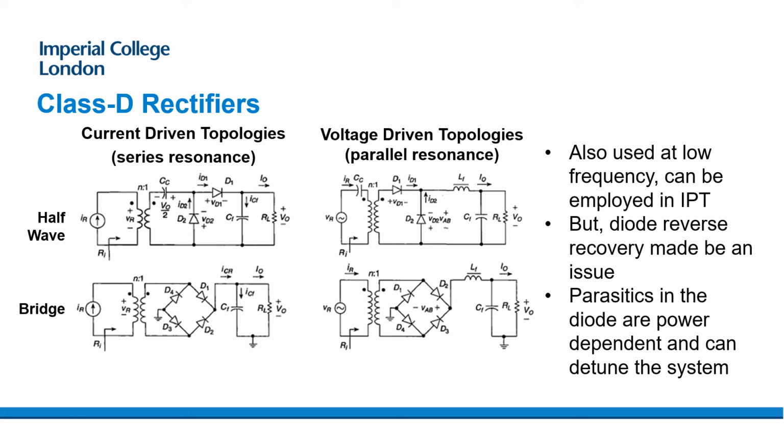Even with your best design, you've chosen series resonance, you've used a topology on the inverter that's able to cope with changes in resistance, you end up getting a change in reflected reactance as well because of the behavior of these parasitic junction capacitances, and that will detune the system.